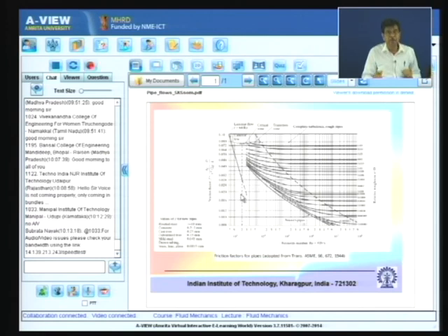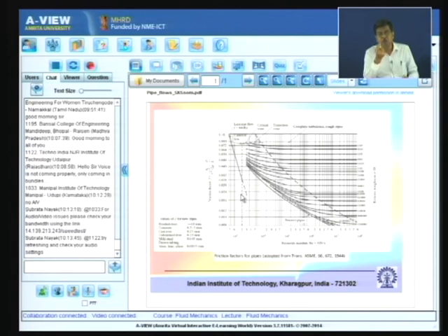Now I give you a physical explanation of what happens in laminar flow. The protrusions or roughness do not make any change in the flow, because any disturbance created by a protrusion is quickly dampened out by viscous damping, since the flow is laminar, unless the protrusions are large enough to create a very high disturbance, and in that case we consider it as a change in the effective diameter of the pipe. So within a certain range these protrusions cannot make any change in laminar flow.